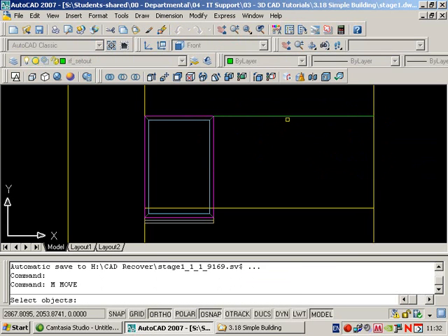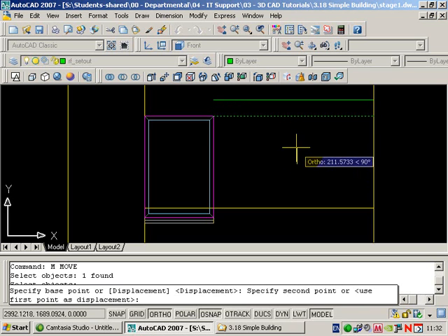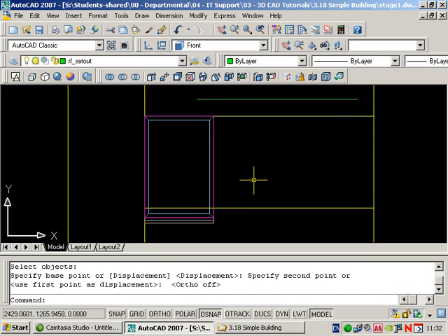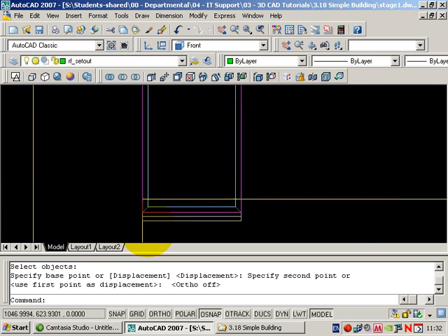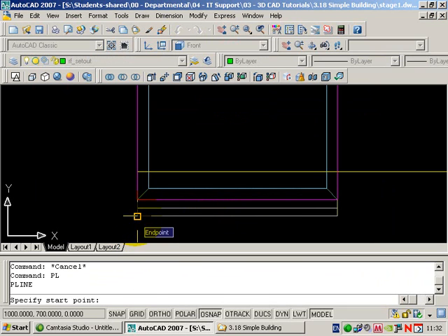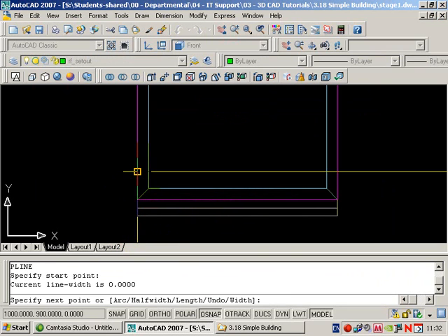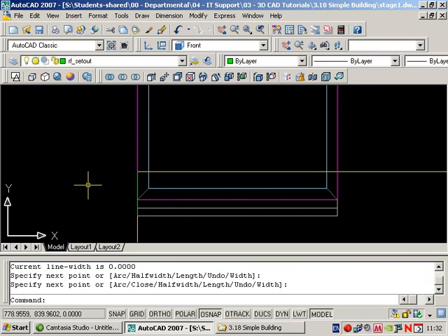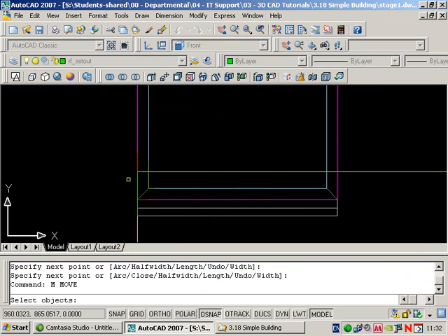Now move that polyline out of the way. Just let it sit in free space. Do the same down at this bottom corner of the window. PL, return, let your O-snaps find an endpoint, to endpoint, and return. You have to be careful that you don't pick ambiguously.